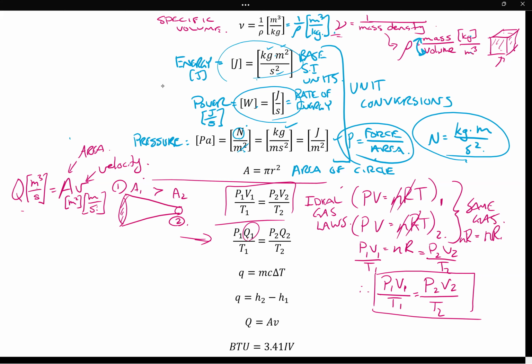So that's what gives you that meters cubed per second. And we can say with confidence that Q1 equals A1 V1 and Q2 equals A2 V2, but volumetric flow rate stays the same. So if 3 meters cubed is going through from here to here, then 3 meters cubed has to go through from here to here too, because it's not compressible. So what that means is it travels a smaller distance here, it travels a bigger distance here over the same amount of time.